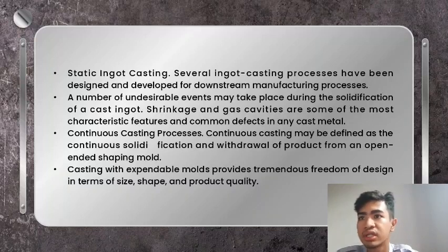The quality of continuously cast metal can, in certain respects, be superior to that of the statically cast ingot. For example, pipe is virtually eliminated. Significant production advantages may also be realized by reduction of the subsequent reduction operations traditionally involved in converting statically cast ingots into semi-finished products.